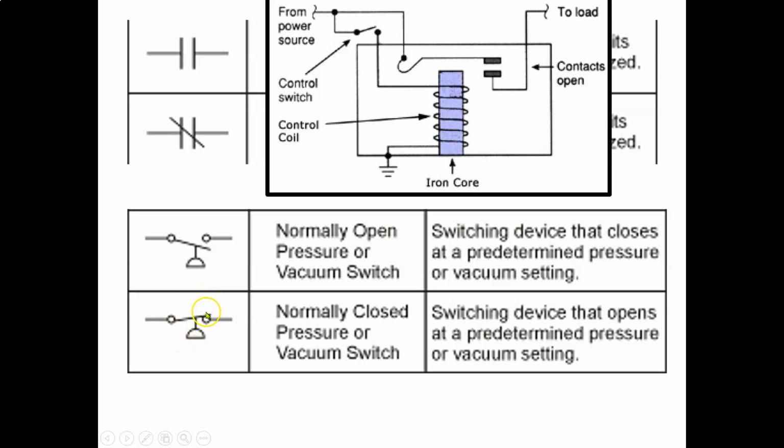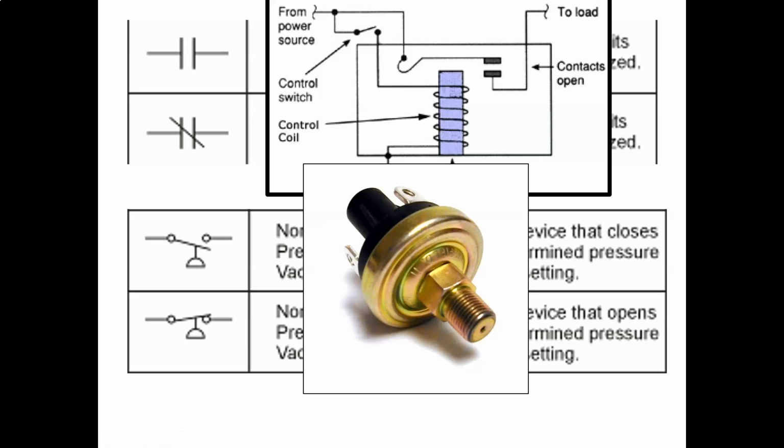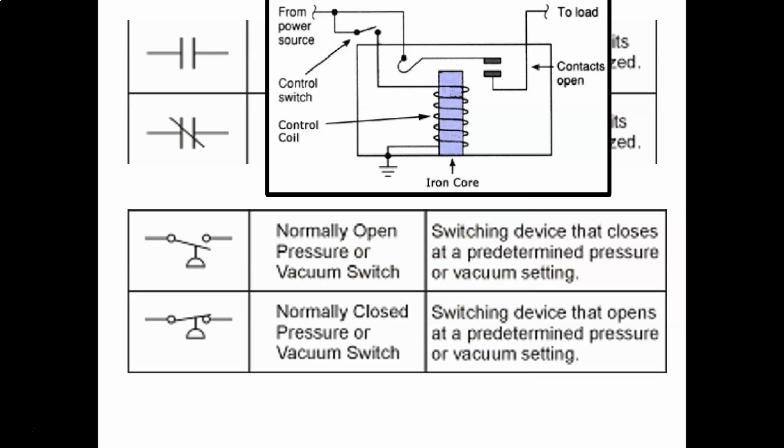And it would still be a normally closed pressure switch. It's just a normally closed pressure switch that has been opened. That's all. So you really have to look at those devices and try to understand what's going on. But before I move on, we always draw devices in a de-energized state, or in a state where there's no liquid, no pressure, no heat.